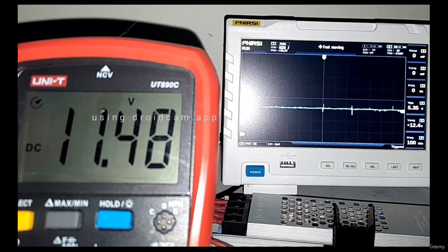accurate reading. In the further examples, you should just understand that the oscilloscope on average adds 1 volt to the readings for whatever reason. It just kind of does that. It might be a slight offset issue, but it's just something to take note of, especially working with this specific scenario example.